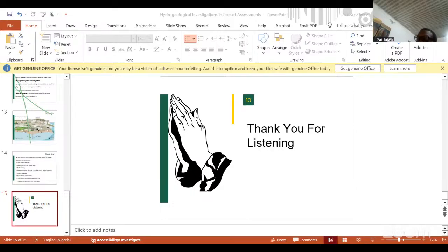It's like this, sir. The relationship of flow in the impact assessment that we keep conducting is quite important. We want to know where this water is flowing, so that whatever we want to do does not impact the flow. What I mean by that is this. For instance, if my flow is from the north to the west, I will want to ensure that whatever I want to site should not be sited in the direction of that flow, so that it does not lead to contamination.